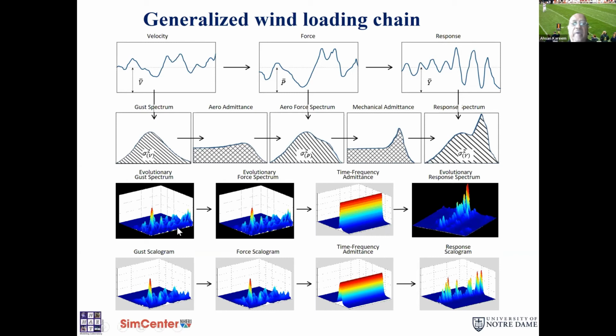So I think that's where I suggest that we should look more into a design evolutionary gust spectrum, just like design spectra for earthquakes. We should look into a similar approach, because otherwise every storm is different. We cannot take care of everyone, but if we standardize that this is what we are going to design for, I think we will have expressions available for all these as well.